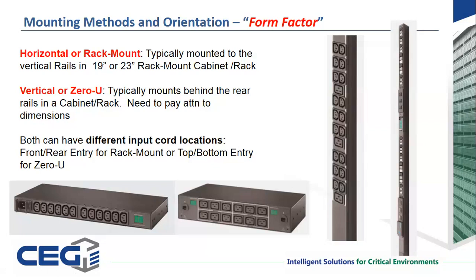Some of the manufacturers, if there's a display on the PDU, the display actually has a little sensor in it that'll automatically rotate the display if you turn it upside down. So you're covered there. It's just the actual screen printed information on the PDU would be upside down. But some manufacturers now are savvy enough to offer input cord locations, whether it's a top entry or a bottom entry. On the rack mount, again, some of the cords come out the front, like the 2 units that you see here, where the input cord locations are.